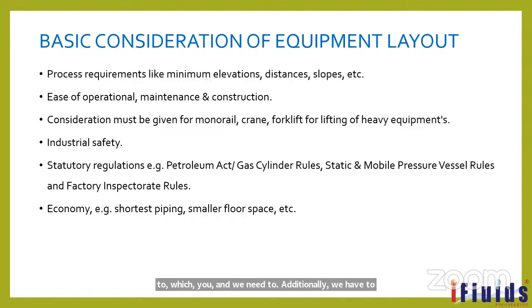All that we can decide only based on the road condition, because heavy equipment like lorry and crane has to go inside and we have to lift the equipment. So all that we need to consider while making the equipment layout.